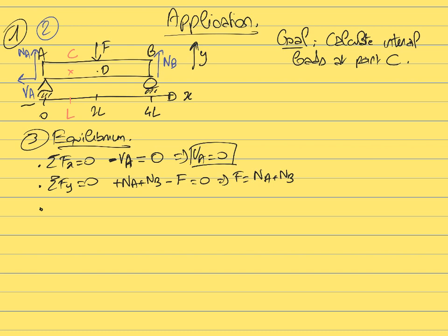You can pick any point to calculate the sum of the moment about this point, but you need to be sure you are consistent between your calculation and the point that you are choosing. In this case, it's always useful to calculate the moment about a point through which you have the most lines of action going through. For example, here, I could calculate the sum of the moment about point A, about point C, about point D, about point B. All of those options would be fine, and you would be able to find the final result, whatever the choice of the point that you are considering.